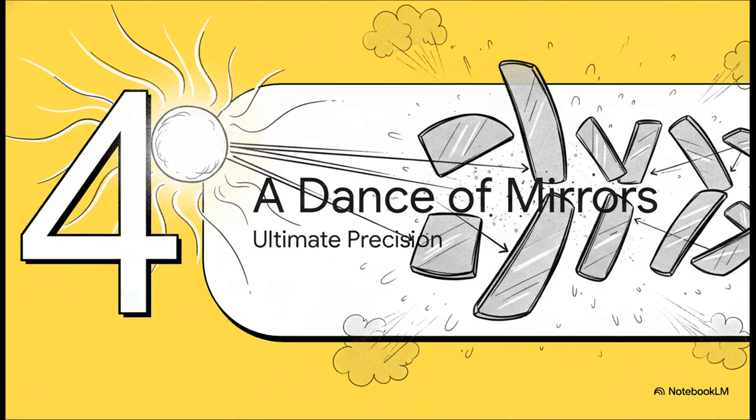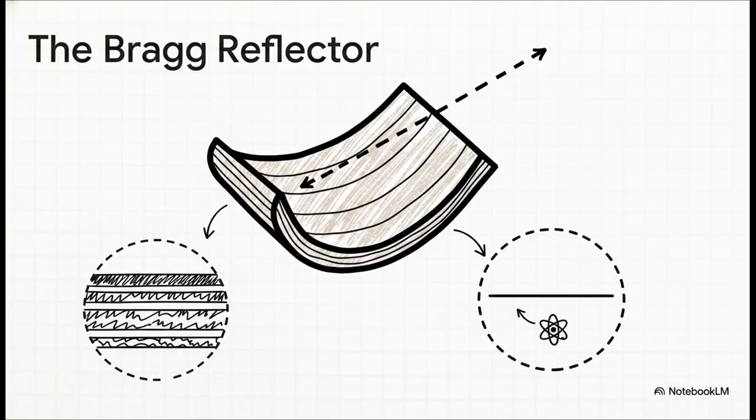You see, EUV light is so high energy that it gets absorbed by almost everything, including air and even glass lenses. So the entire path for the light has to be in a perfect vacuum. And instead of lenses, the machine has to use a series of the most perfect mirrors ever made by humans. And these are not like the mirror in your bathroom. They're called Bragg reflectors.